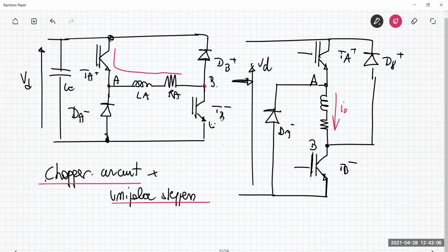But remember that this circuit has the ability to generate a reversible voltage, which is what I really need for having a faster turn on and turn off action. So this is what I require: a two-quadrant converter having not bidirectionality of the current, but reversibility of the voltage. We derive the same circuit, the same topology, starting from the four-quadrant converter, which is the most general circuit that can be employed for the DC operation.